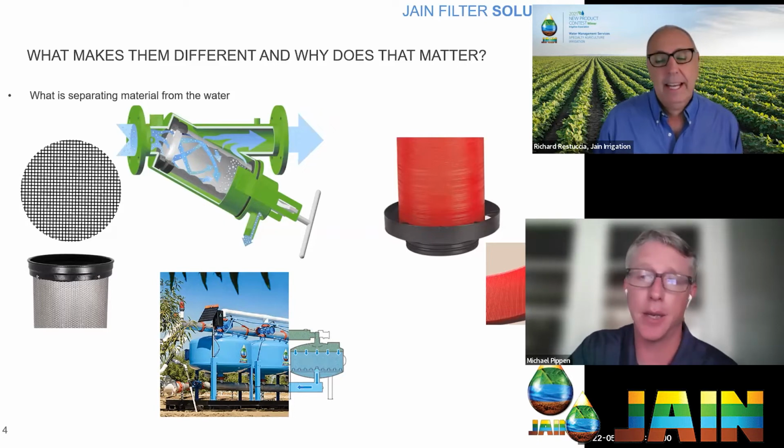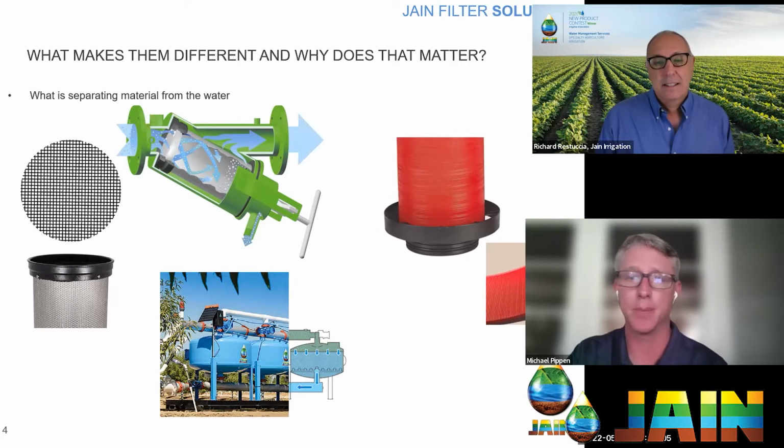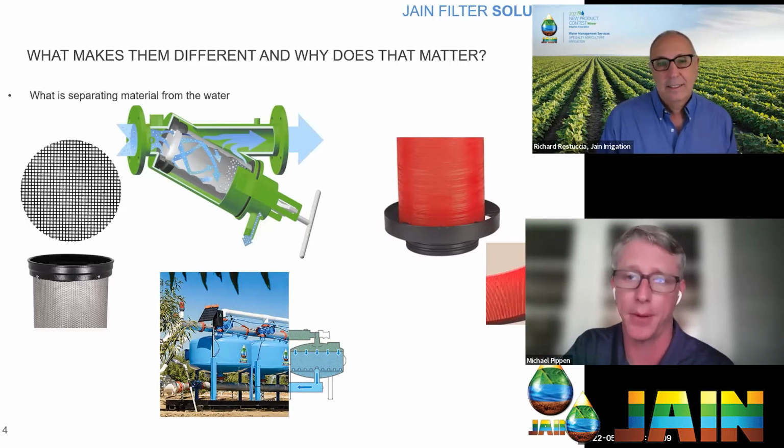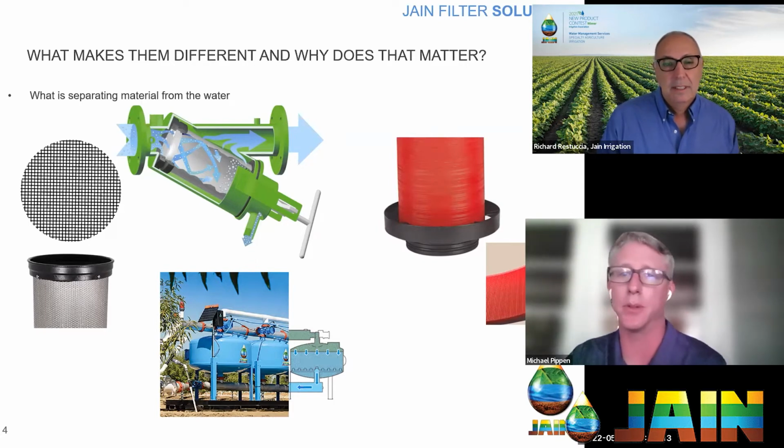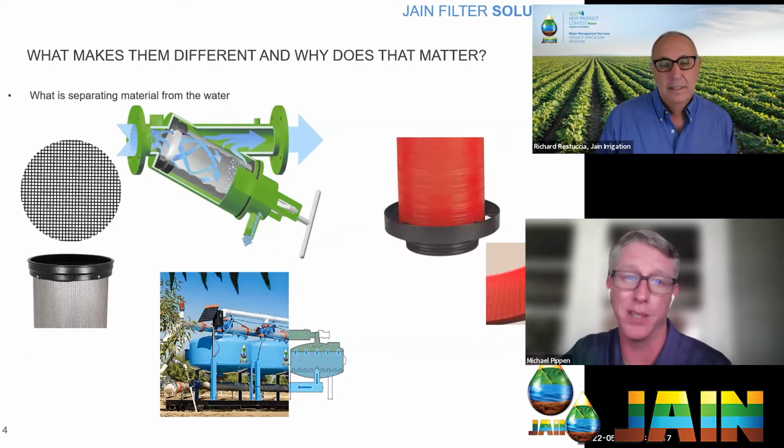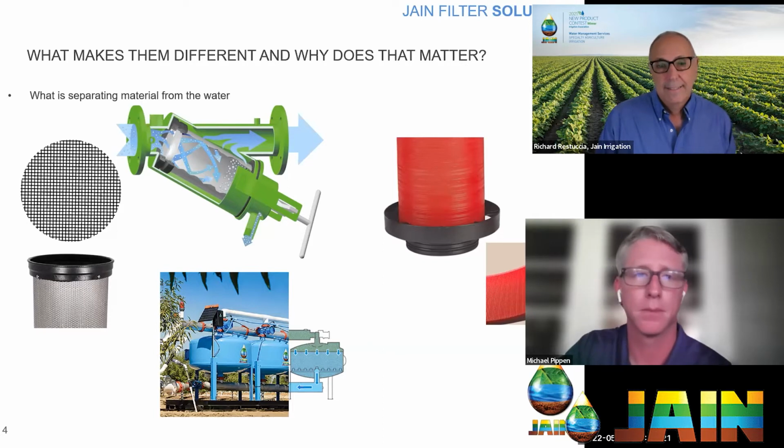That's correct. And in some applications, that's all you ever have to do, depending on what you're collecting. Sometimes you can open this up at the end of the day and flush it for 5 minutes, and you never have to take out the cartridge. Most of the time, people don't get away with that, but it is possible in a really clean water application where the spinning feature is good enough to not have to take out the element.